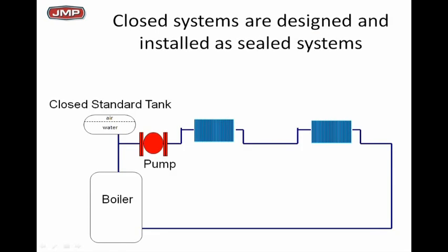So let's look real quickly at a closed system. Now, what have I done now? My expansion tank is now closed. It's under pressure. It is sealed up with mechanical seals, manual air vents. No way for fresh water to be leaking from it, no way to bring in oxygen. And I've seen closed systems 10, 15 years old that the water is very clear inside, that the piping inside is clean, because when you close it up and seal it off properly, you start with some air, but air is 80% nitrogen. So that original air charge has 20% oxygen, roughly 80% nitrogen.